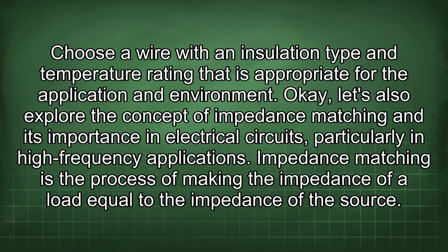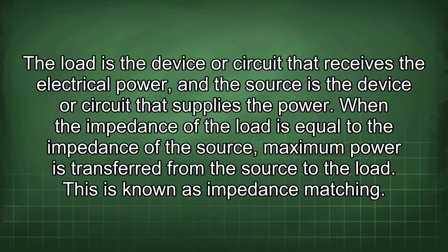Okay, let's also explore the concept of impedance matching and its importance in electrical circuits, particularly in high-frequency applications. Impedance matching is the process of making the impedance of a load equal to the impedance of the source. The load is the device or circuit that receives the electrical power, and the source is the device or circuit that supplies the power. When the impedance of the load is equal to the impedance of the source, maximum power is transferred from the source to the load. This is known as impedance matching.